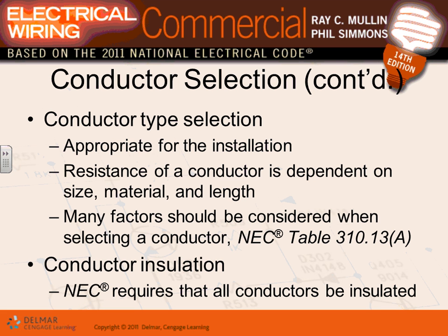3 things you have to take into consideration when you size a circuit. That's why when you get into engineering firms, you can find them throwing a lot of circuits. Every 20 fixtures, they throw a 20 amp circuit, even though you could have put another 20 fixtures on the same circuit. Voltage drop is a big deal, so keep this in consideration.